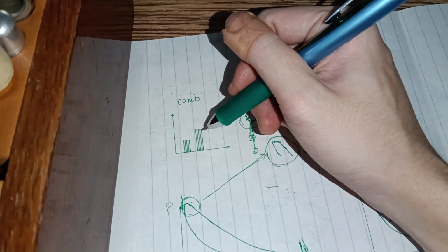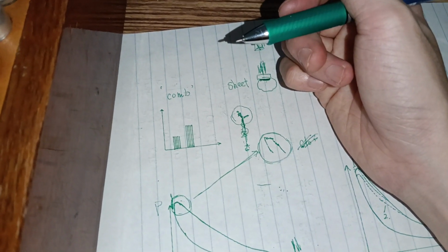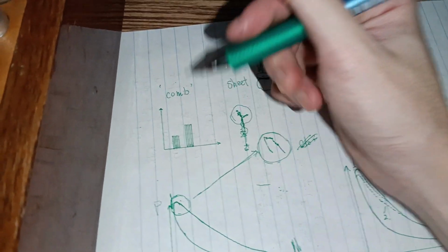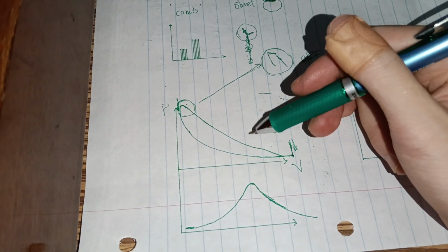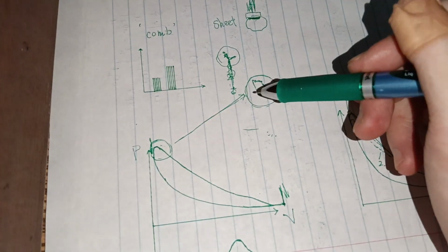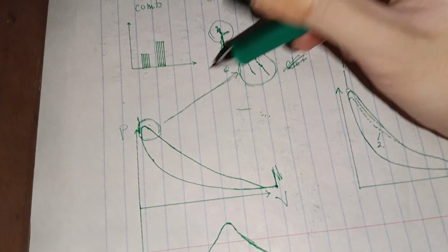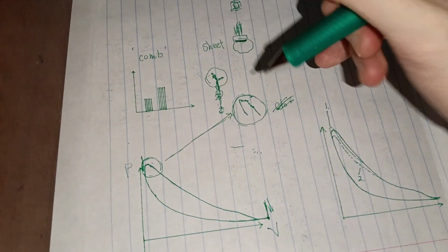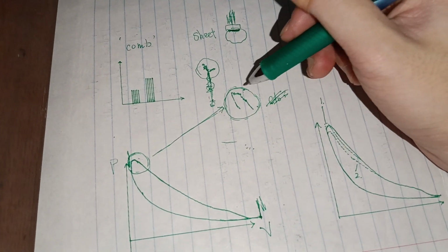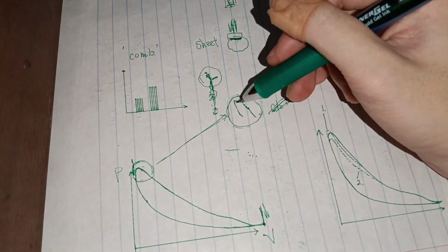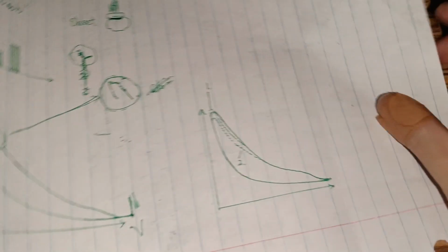Now you understand that this is usually used for tuning the firing pressure, the fuel pump, like the fuel index, or the injection timing. These two are the normal diagram graphs, and if you happen to have a shape like this in this part of the diagram, it means you have a clogged injector or clogged fuel valve.